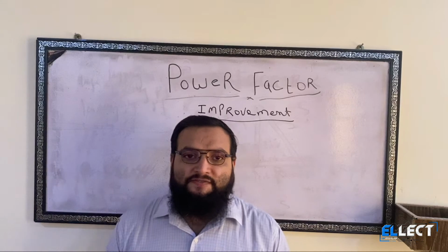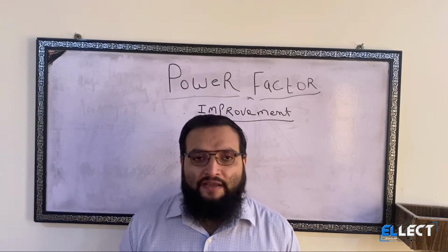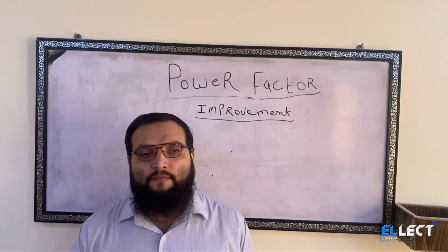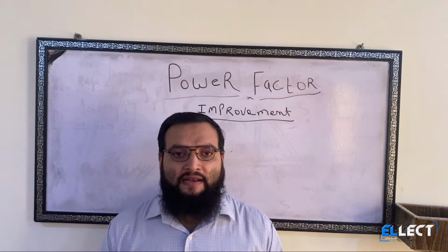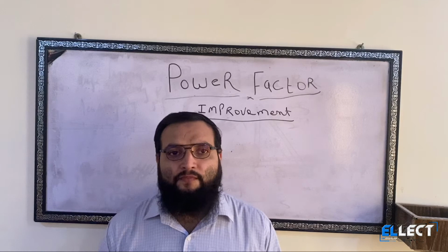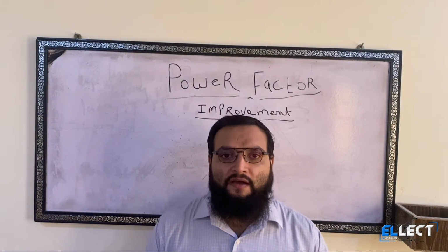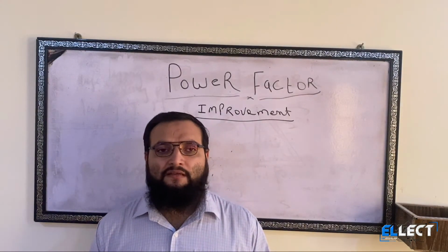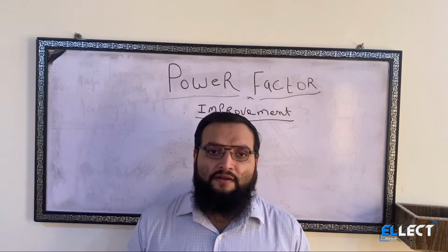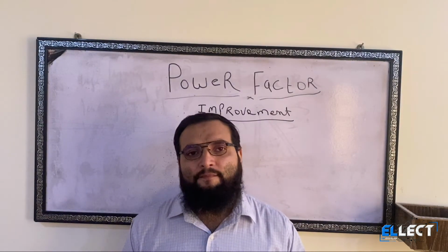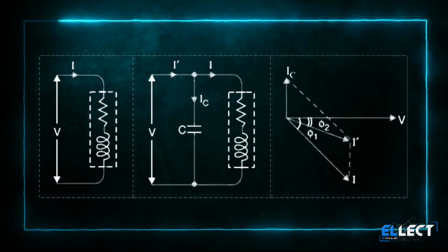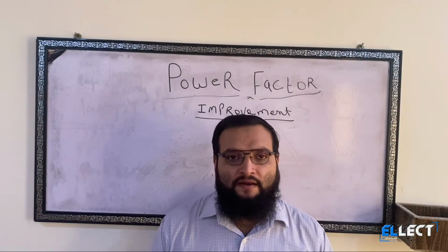Whenever the static capacitor is connected in parallel with the device that is working on low power factor, it decreases the lagging component by improving the leading component of the current. But one thing should be taken into account: it only improves or eliminates the reactive component of the current, but it does not disturb the active component of the current.